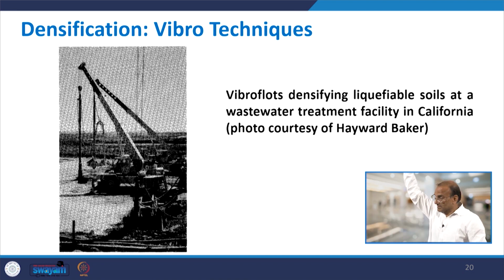It is kind of a torpedo-like hammer, and it will generate lateral movements in the soil. So, it will densify not only at the point, but within some radius around the point, because it creates horizontal vibrations and densifies the soil.